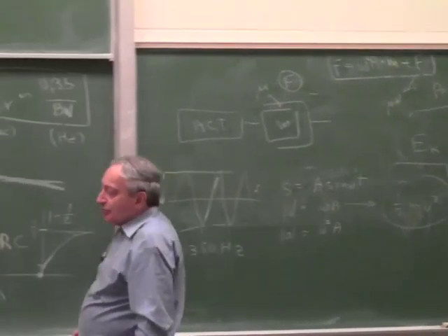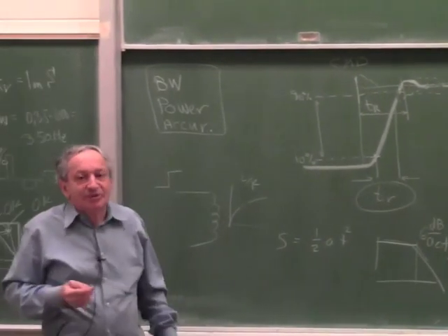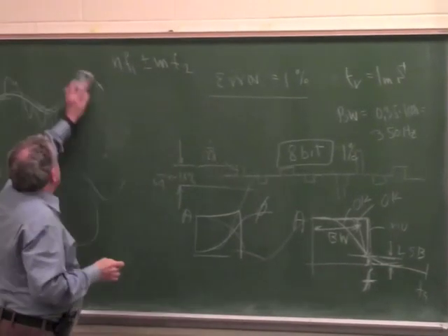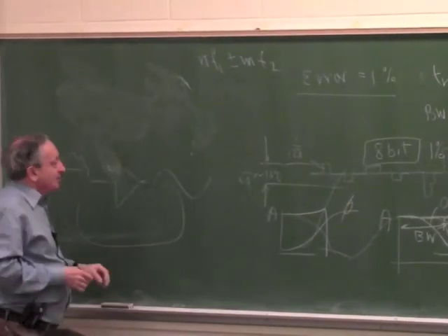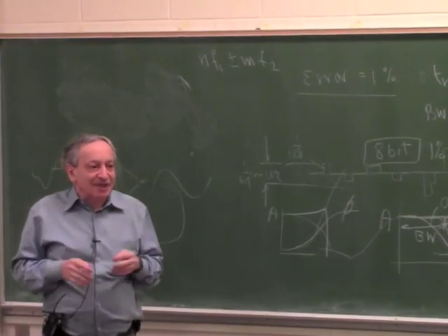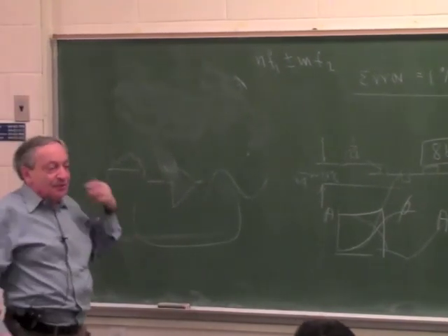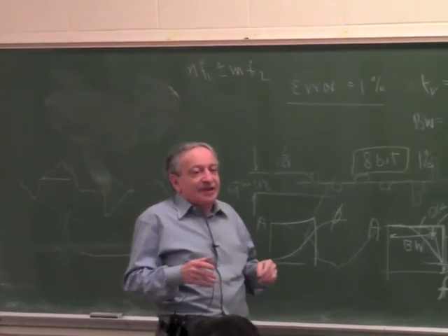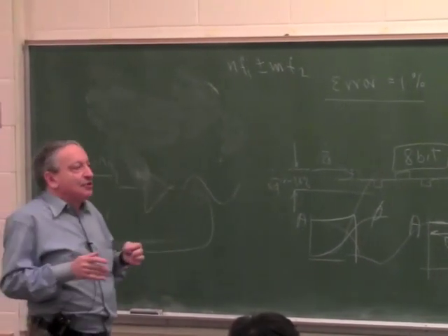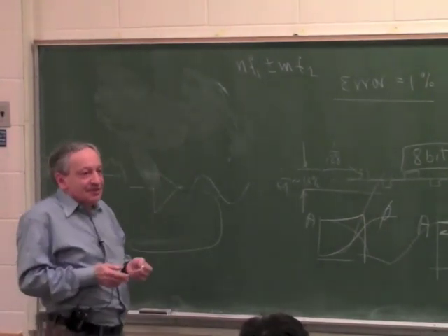Now, the usual pitfall whenever you calculate heating of something is that people use the average instead of the RMS, and we went through it enough times that I don't think you need to be reminded. Because you have to know when to use the average, when to use the RMS. It depends what you're trying to find out, but the main thing is if you're worried about heat limit, like steady state limits, heat limits, you have to use RMS.